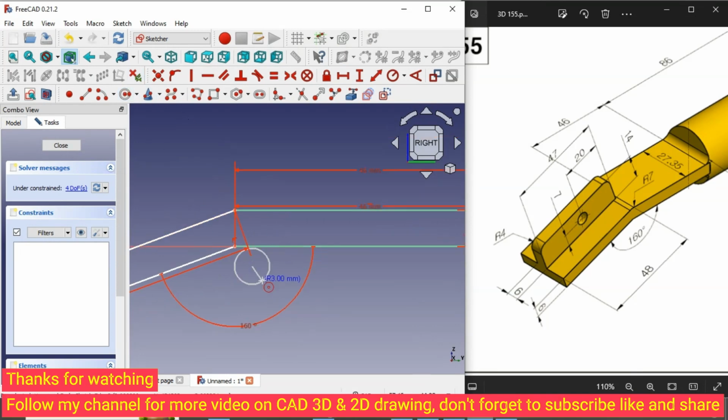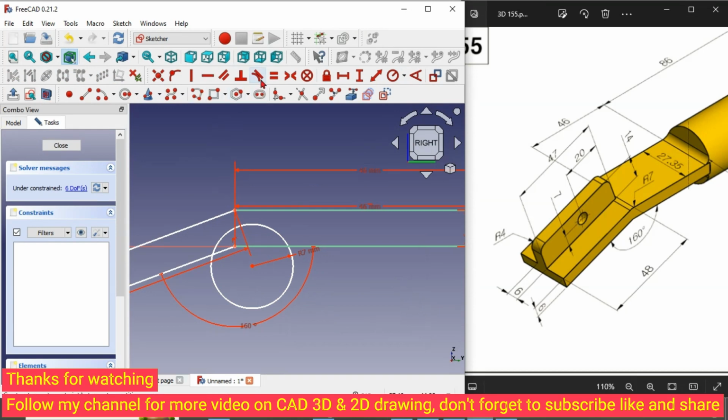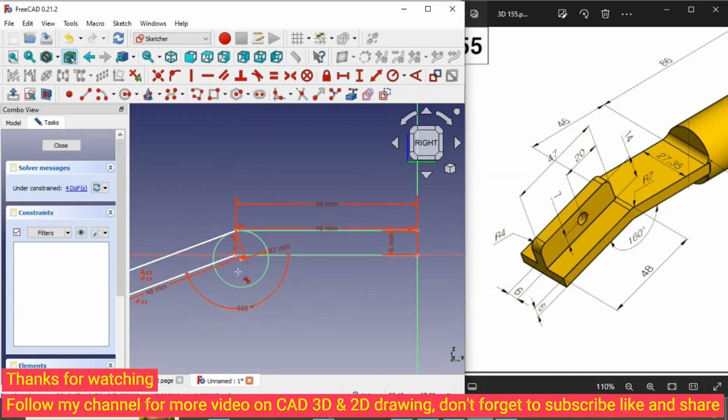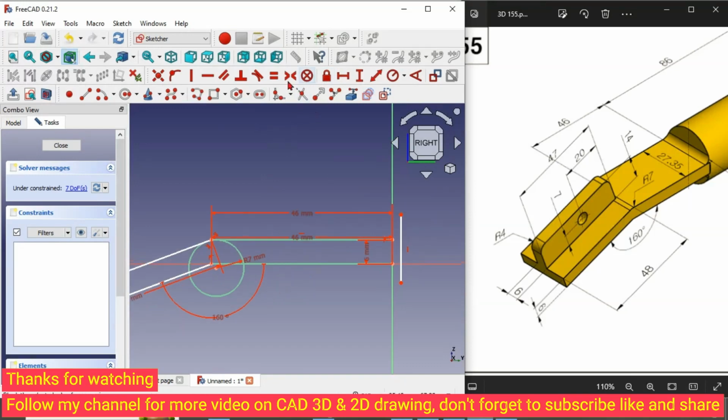So we draw a circle, then we set the radius 7. Then we make it tangent to this, and also this to this tangent. Okay, done here. One more thing. This line should be closed, so we make it vertically constrained. Then we make it constrained to this point.